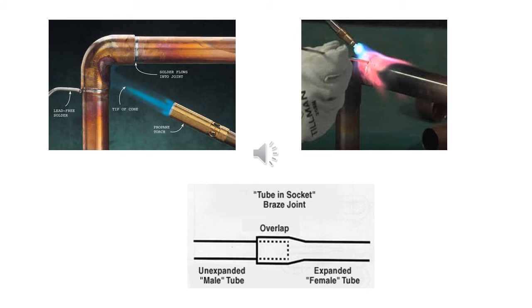The most commonly used brazing filler metal types used to join copper pipe and fittings fall into two distinct categories. BCuP alloy, where B stands for brazing, Cu is the chemical symbol for copper, and P is the chemical symbol for phosphorus. Therefore, a BCuP brazing alloy is primarily a copper-phosphorus brazing alloy that may contain from 0% to 30% silver. BAg alloy, where the B stands for brazing and Ag is the chemical symbol for silver.